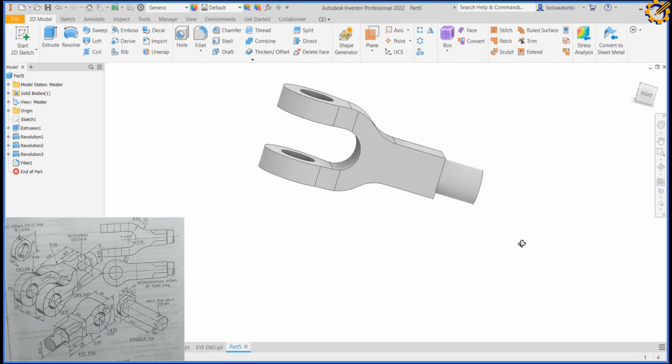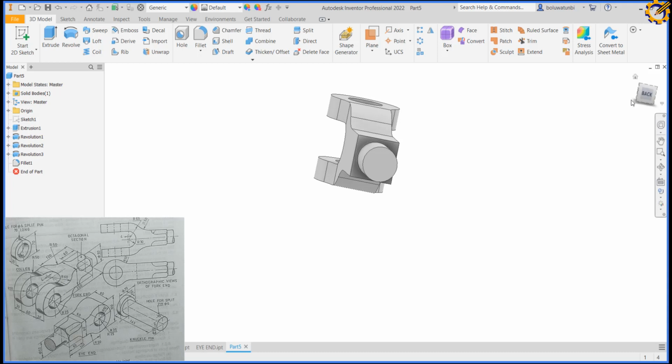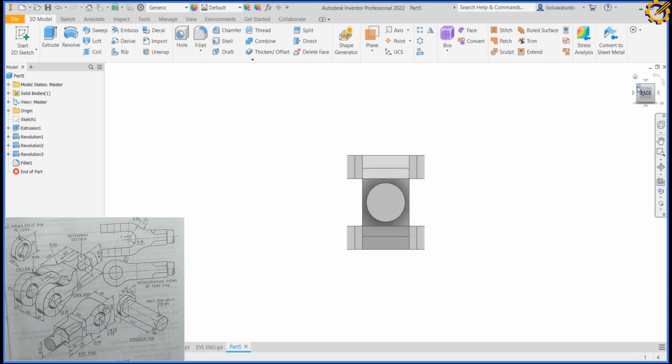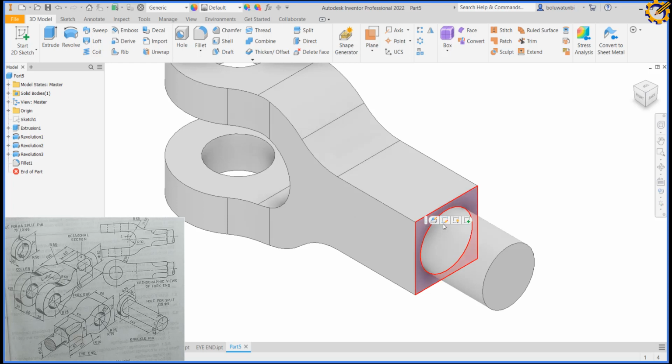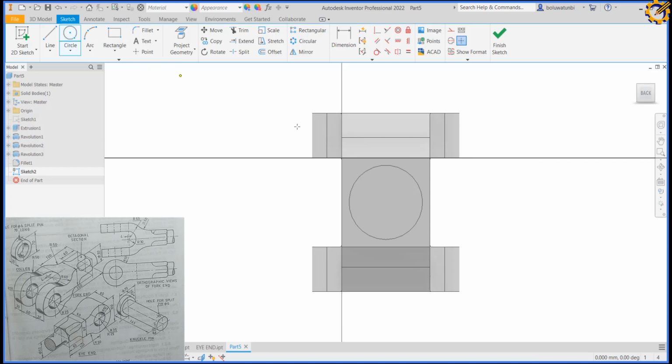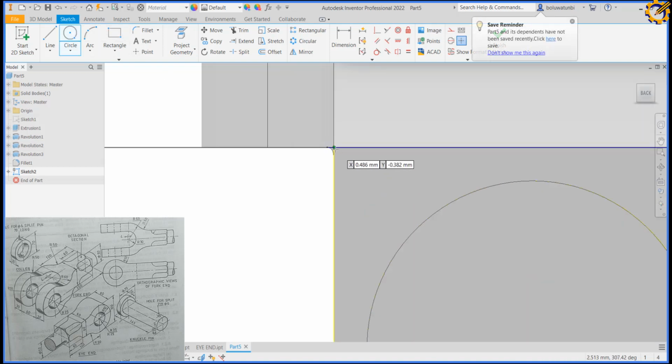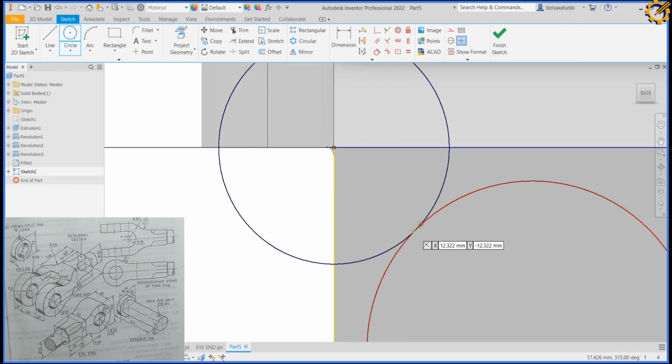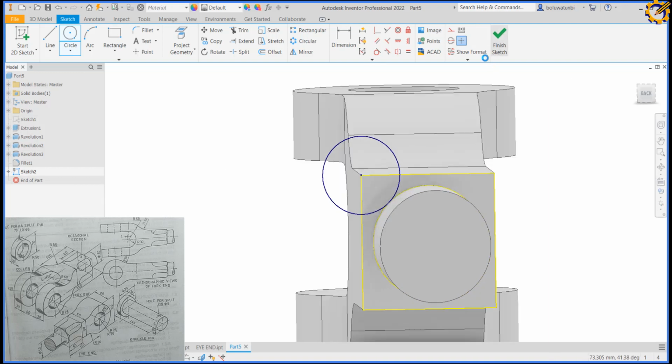So it remains that area at the back. So likewise with my object tilting this way, I click this surface, I create sketch. Creating my sketch, I pick my circle, I stand at the edge right here. You see that? Or if you want to see what I'm doing, just click on project geometry, click the surface, then what? Okay, you see the yellow line. So with my circle, start at this edge right here. So I draw a circle tangential to this. Do you see that? Then I finish sketch.